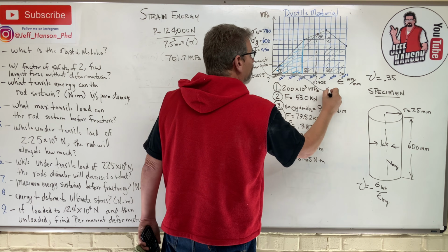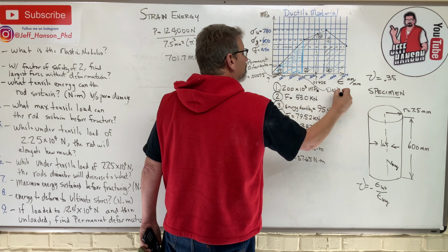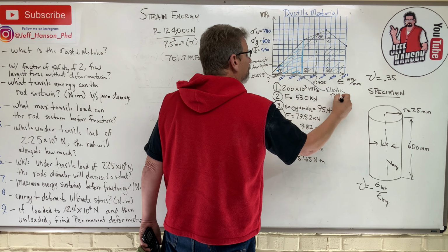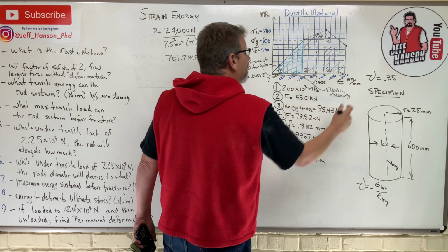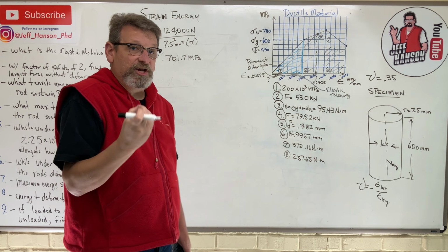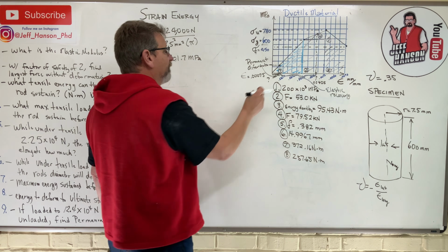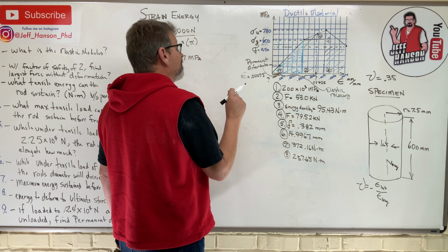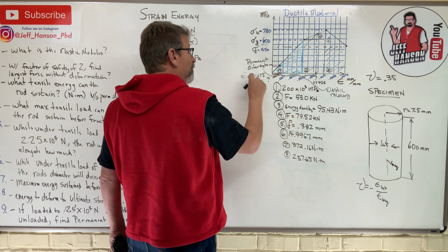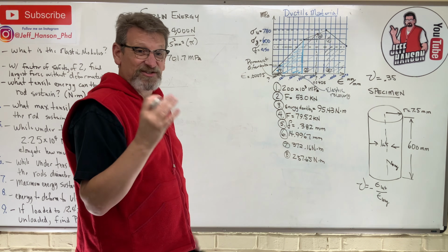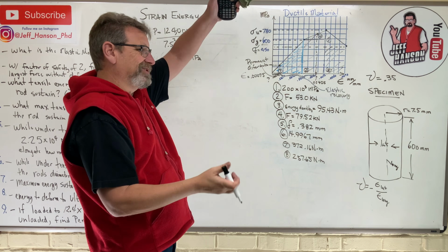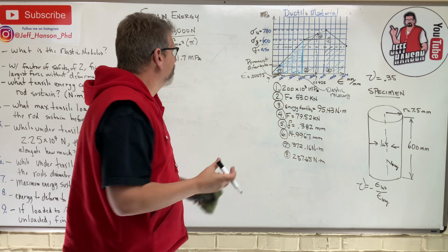That is called the elastic recovery. That is how much the material recovered in inches per inch, right? So that's the elastic recovery. This is the permanent deformation. So that thing deformed, we stretched it too long, right? This is like your slinky, your little sister stretched, and it didn't go back to where it started from, right?